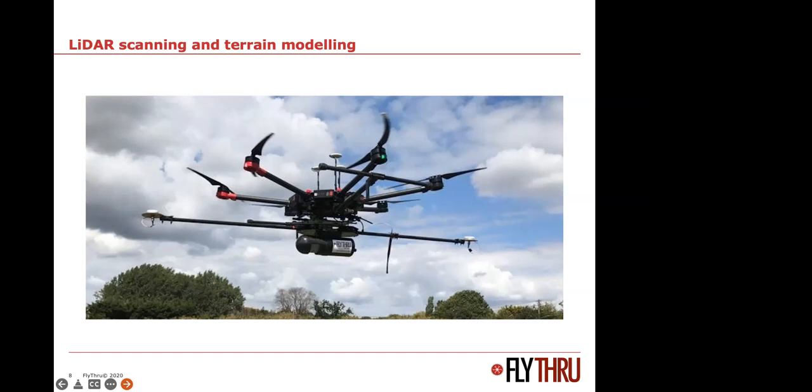What you end up with, if you don't know how to plan the flying properly, is a lot of data that's captured very quickly downwind and stuff that's captured very, very slowly upwind. So one of the base things that we talk about when we go to any site is find out where the wind is coming from, and we fly crosswind everywhere. As it's the same with the fixed wings, because obviously they've got to turn into wind and not downwind.